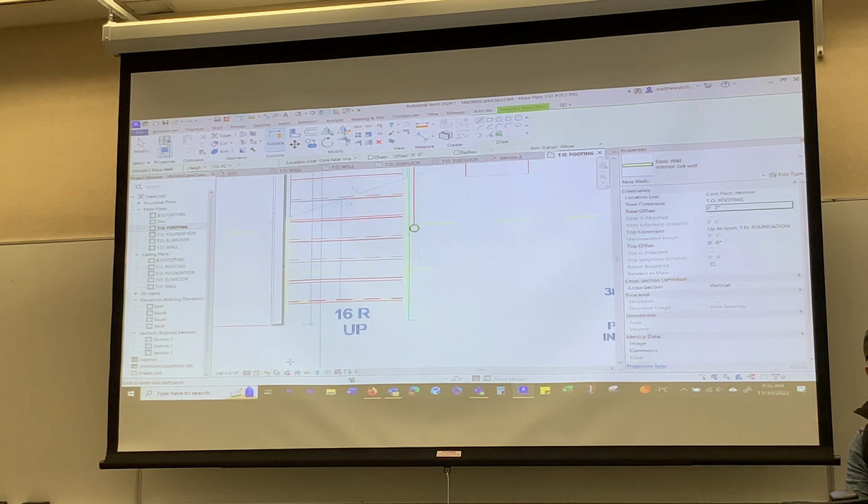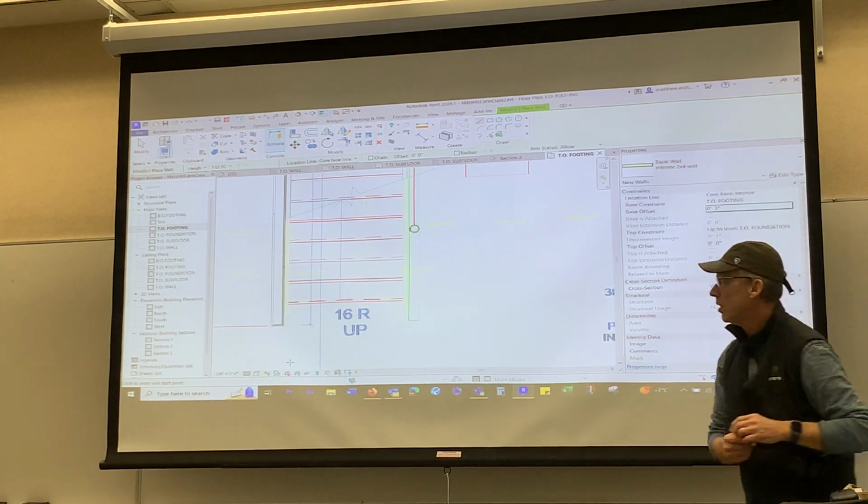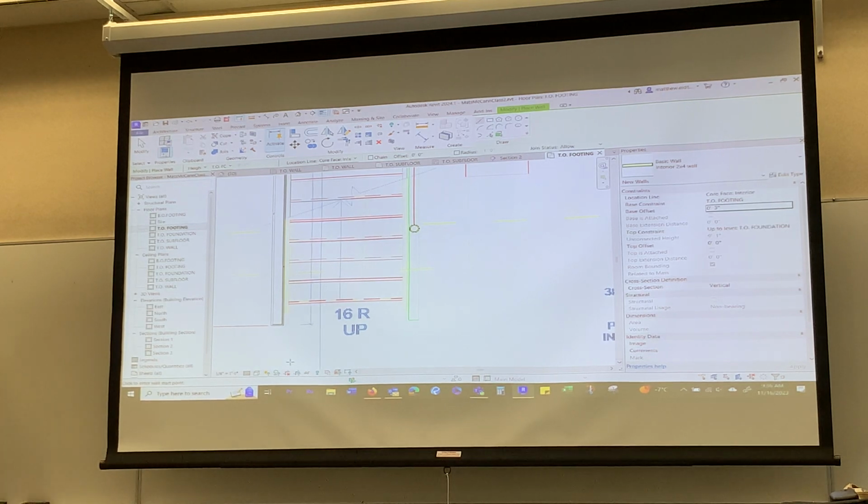If you cut the stairs in section, you're going to have the stringer. The stairs are going up this way, and this is the stringer that goes down on a slant. For those of you who don't know, that's the stringer, and the steps go like that. Then you put carpet or hardwood or whatever after the fact. This is the framing, a 2x4 wall. I've got drywall on the outside, and I'm going to have to have drywall on the inside. They make them a little bit less than a half inch each side, but usually they have a 1x4 on here.